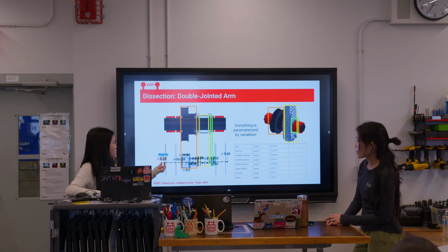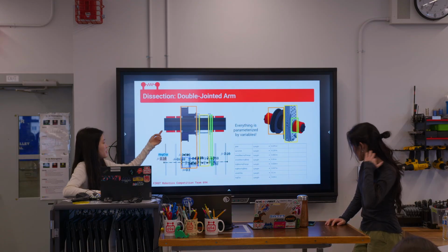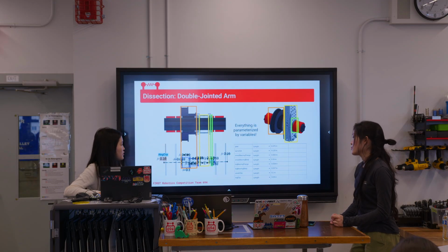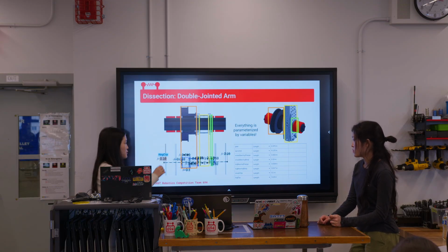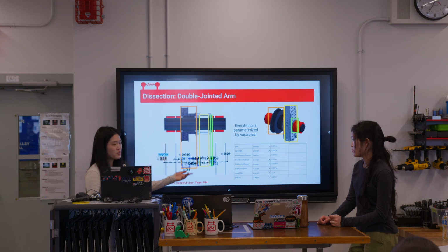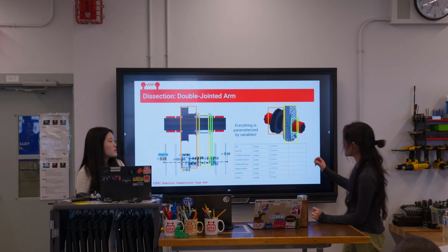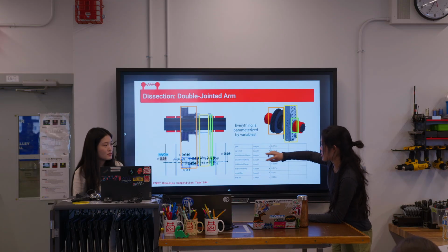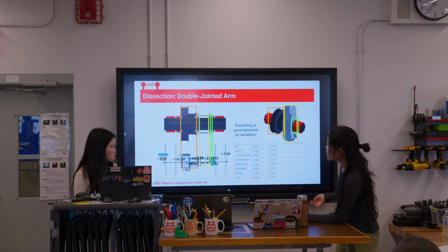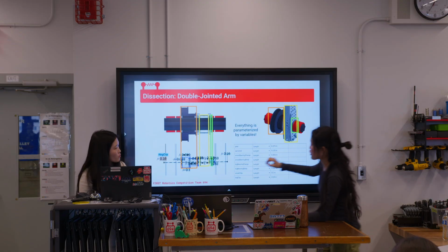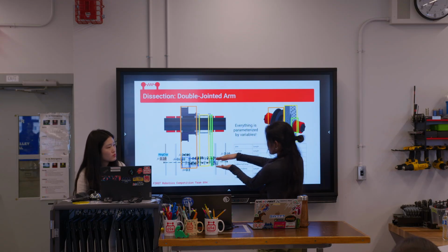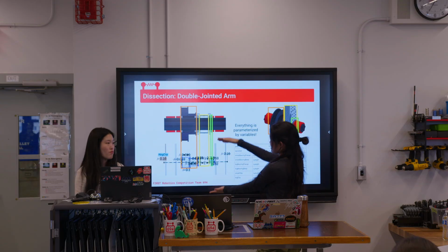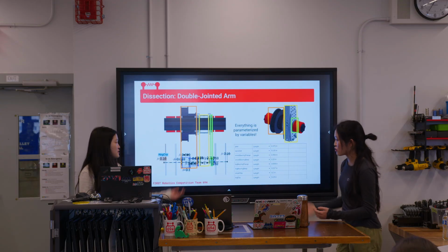And even the C-clip sticking out, because a retention clip is going to go on top, you would have all of that represented. And if you notice that this part is blue, this is a personal preference. I like to save loading time, so I don't define the length this way because I care about the length this way. But how someone else might do it, I sometimes use the axle sketch itself to create spacers, because you could just revolve around to create the spacers, which is why someone like me might define the dimensions of the pulley in this dimension, and the bearings in this dimension. It might be a personal preference, but you don't have to define everything.